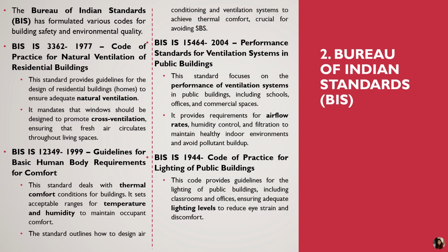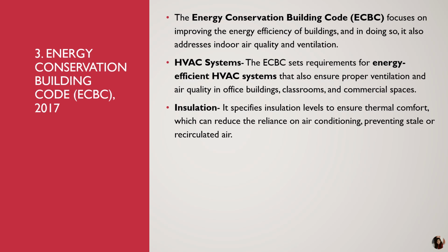Also, BIS 1944, the code of practice for lighting of public buildings, ensures that we reduce eye strain and discomfort in classrooms and offices. So this is about the Bureau of Indian Standards. Another one is the Energy Conservation Building Code, ECBC. Here they focus on improving the energy efficiency of a building, and HVAC can be used efficiently to have proper ventilation and air quality, and insulation to ensure thermal comfort and reduce reliance on air conditioning, preventing stale and recirculated air.